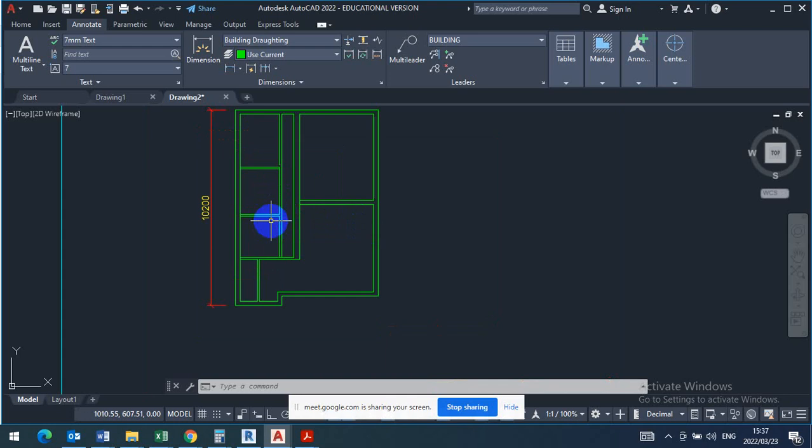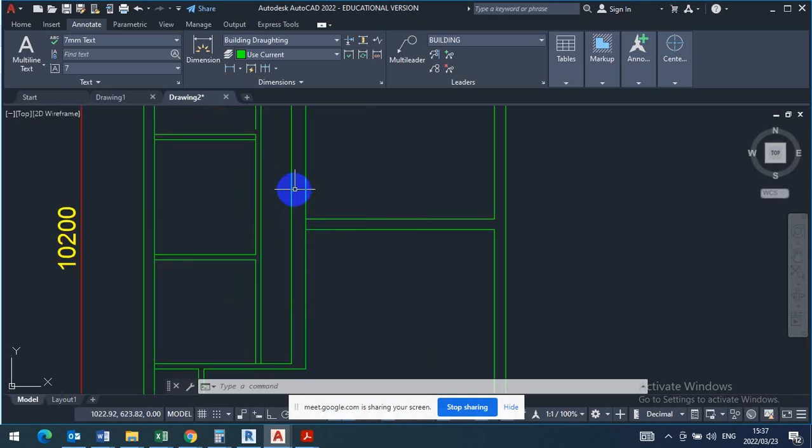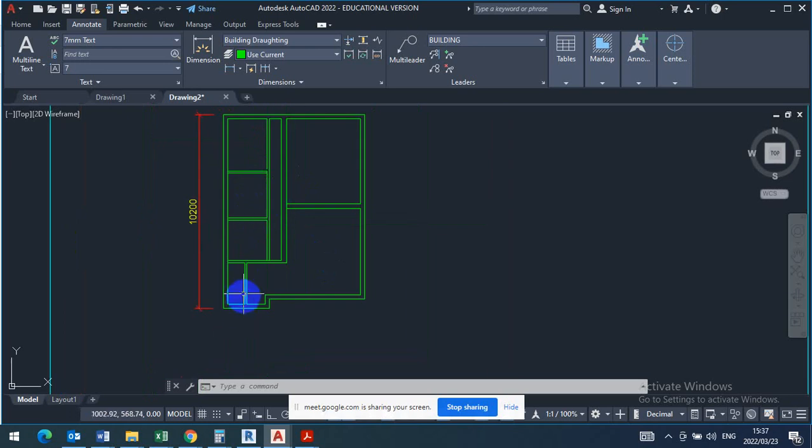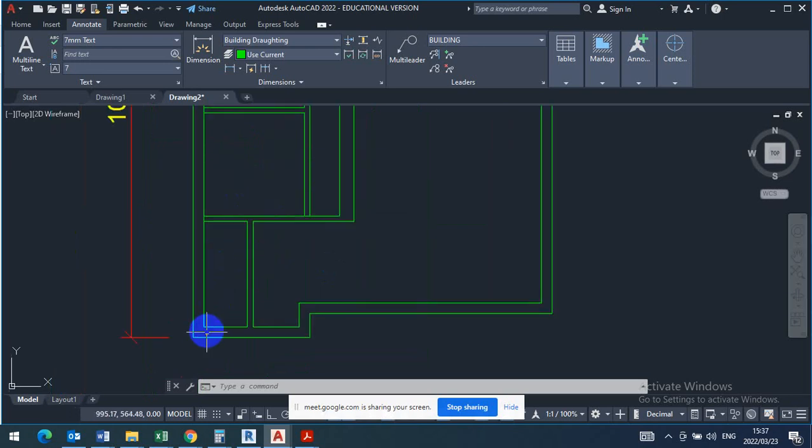room sizes. When I'm designing here, whatever I was doing here, must follow South African building regulations. There are room sizes according to standards. We don't just design rooms our own way. So there are standard room sizes like a kitchen, a bathroom, a passage. I told you that is 900 minimum for the passage. When we go to the patio, it should be at least 900 by 1.2 meters.